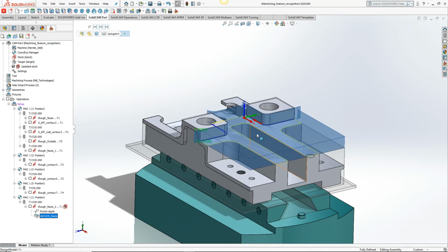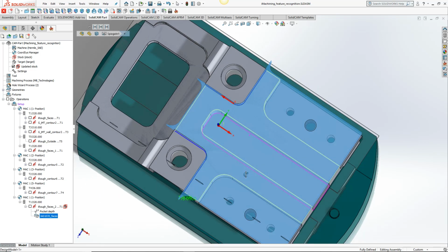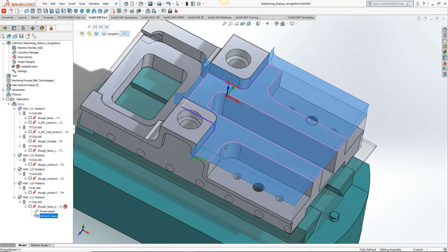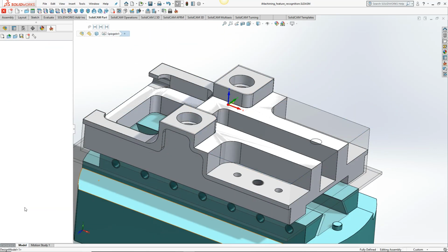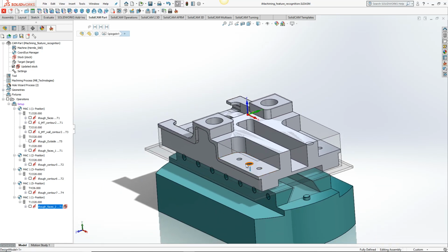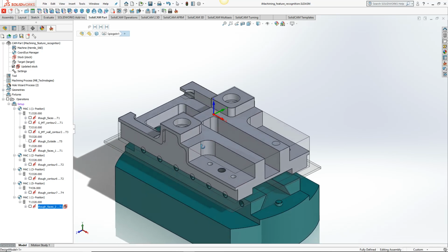And we also have geometry preview from the CAM tree. So if you click on the geometry, you can see exactly the face that we selected, and you can see it extended and trimmed out everywhere to machine that feature. And that can also be extended to cutting multiple faces with variable depths at the same time.